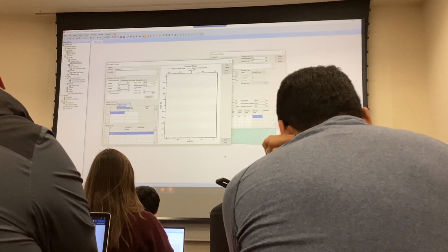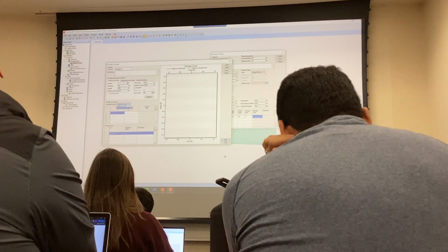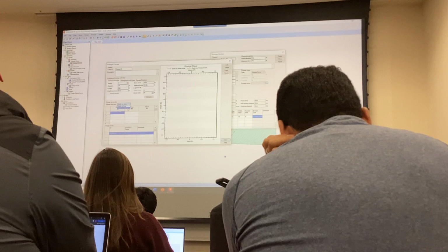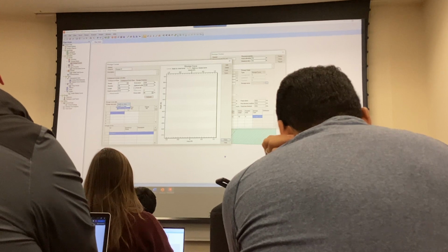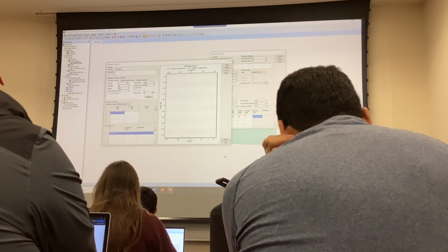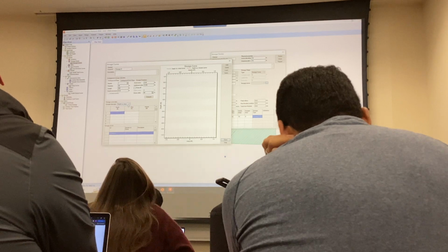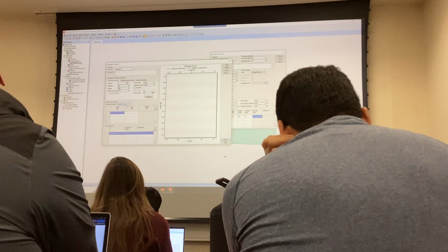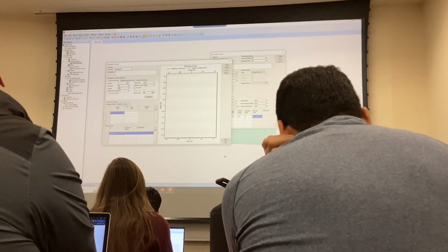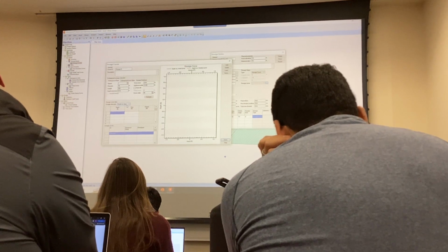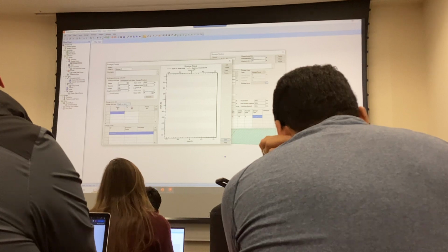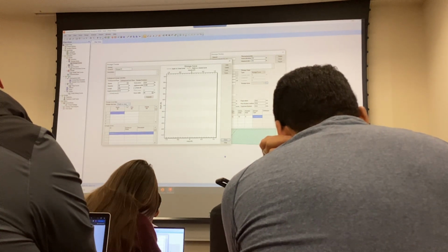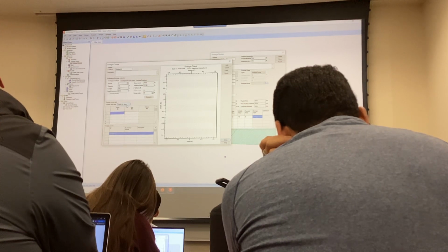So let's say hypothetically I already graded my detention and I do have the contours available. So I can now put in the depth versus area. Depth starts from 0. Elevation, unless you're at mean sea level, you are going to have a certain amount of elevation regardless. Are we on the same page?